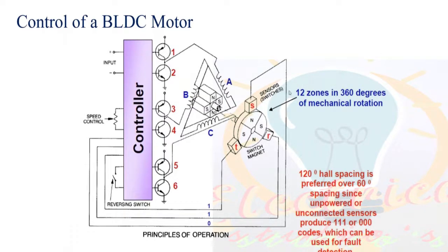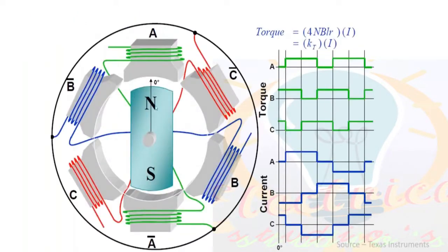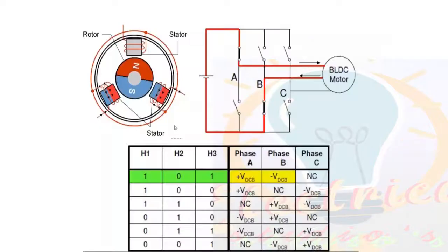So depending upon the signal I get from the sensor, I detect the position of my rotor, right? Whether my rotor is in this position or this or this. Where it is aligned, I determine with the help of my Hall sensor. After determining that value, I switch on the next switch to move the position from this to this and from this to this.